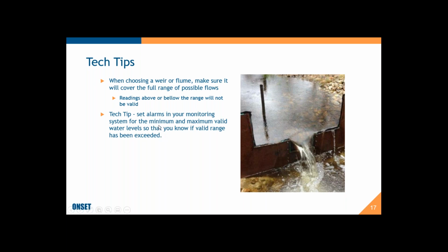I would recommend setting alarms on your monitoring system, if your system has that capability, for the minimum and maximum valid ranges for your water levels, so you can at least know when you're outside of a valid range for measuring flow.